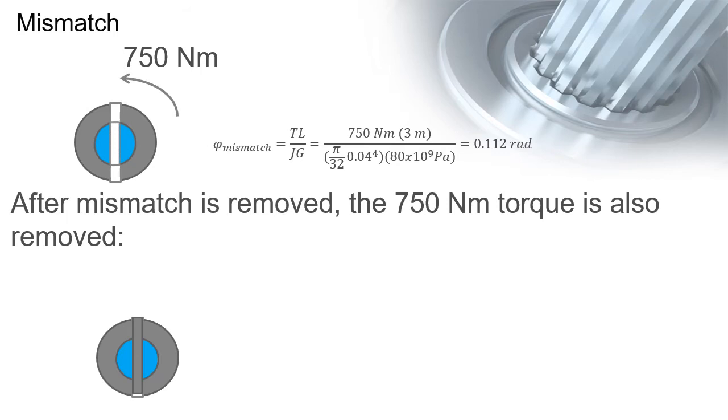Since the material should behave elastically and both shafts are fixed at one end, the steel shaft end tends to go back to its untwisted state. The steel shaft would want to go back to its initial position because it behaves elastically.